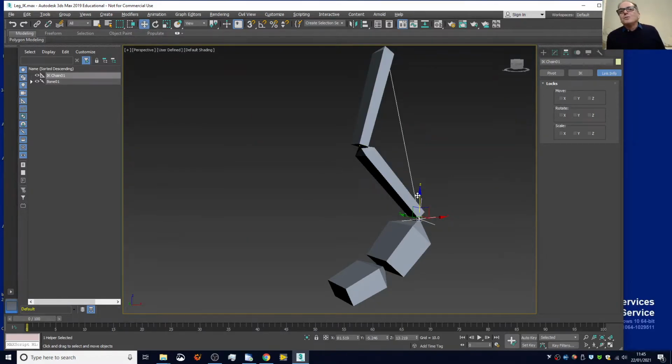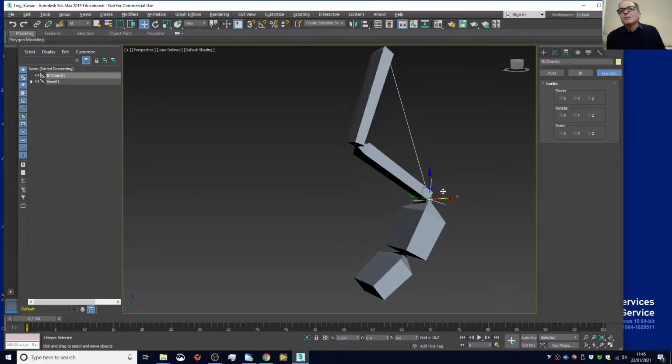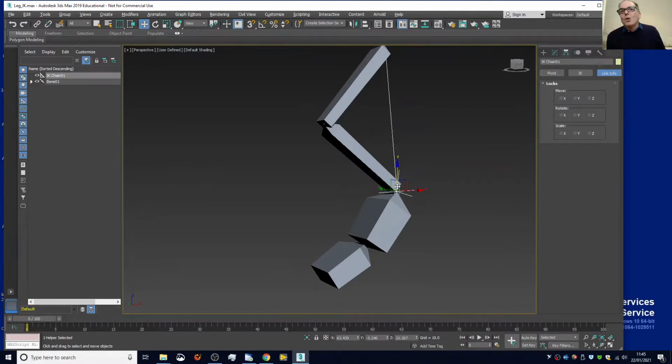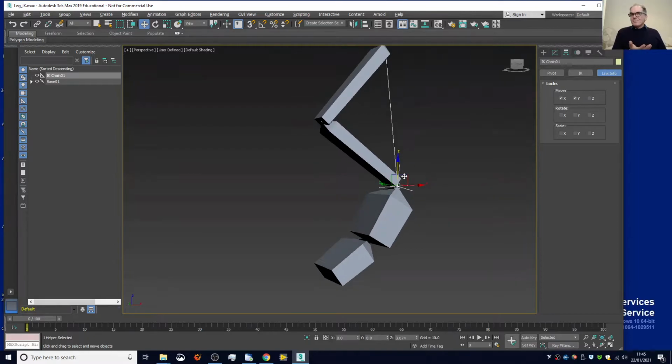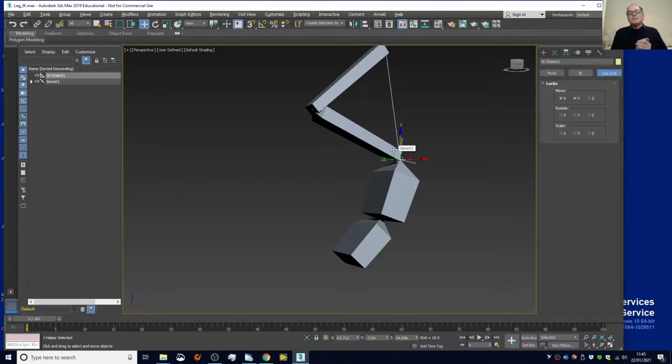So when you do a movement, you can see that now all of that moves, but we can restrict that. So we can move it in the Z, Y plane. And what we can do now is select the link and restrict it to moving only on the Z plane, for example. So we restrict the movement here and here, and then when you try to move, it doesn't move on the other. So we can constrain our joints, our pivot. And that's what's very important.